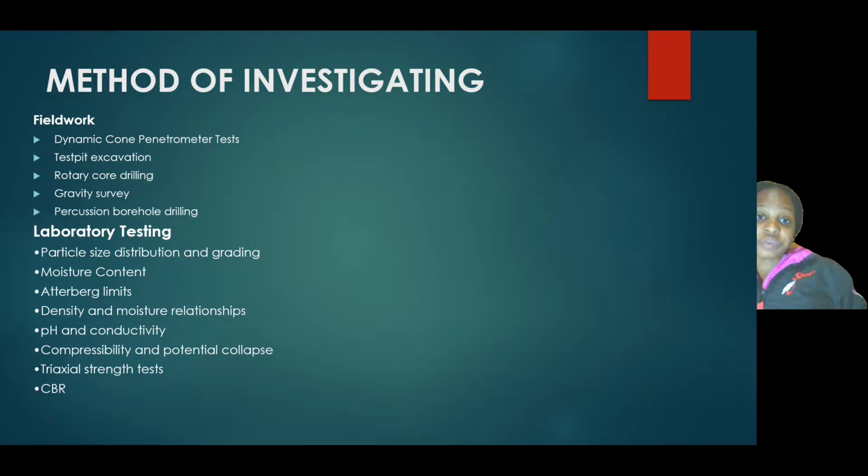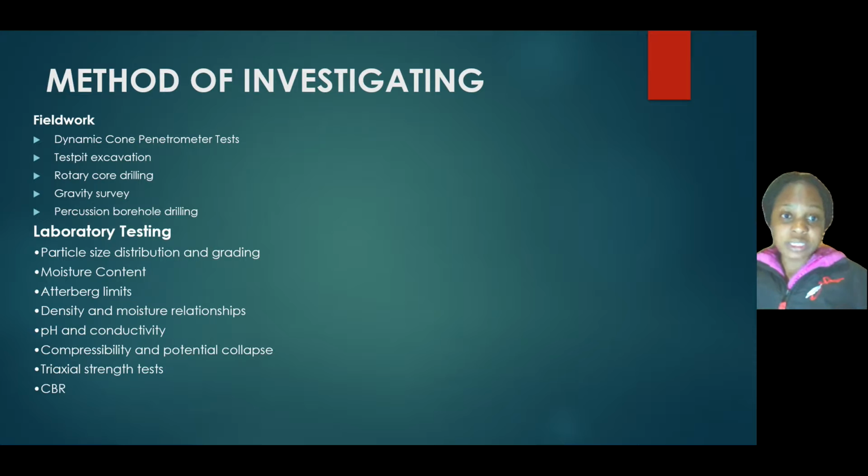We move on to method of investigation. We've got two methods of investigation. One is fieldwork, the other one is laboratory testing. On fieldwork, we'll consider dynamic cone penetrometer tests, test pit excavation, rotary core drilling, gravity survey, and percussion borehole drilling.